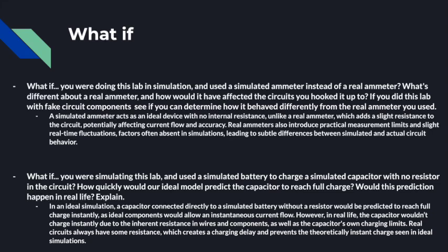The second what-if was, what if you were simulating this lab and used a simulated battery to charge a simulated capacitor with no resistor in the circuit? How quickly would your ideal model predict the capacitor to reach full charge, and would this prediction happen in real life? In an ideal simulation, a capacitor connected directly to a simulated battery without a resistor would be predicted to reach full charge instantly, as ideal components would allow an instantaneous current flow.